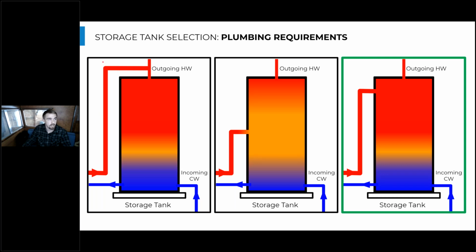And while the heat pump's off, there's no water flowing through here, so you get a cold line of water. So every time your heat pump turns on, it's sending that hot water directly to the outlet that's going to the mixing valve. So there is a short period of time before your heat pump warms that loop up all the way that your occupants are going to see cold water if you eject your hot water straight to the outlet here.